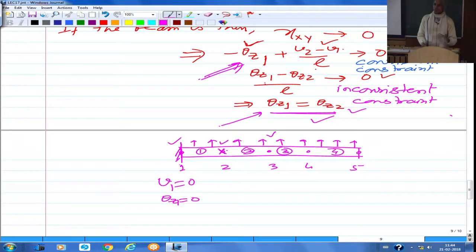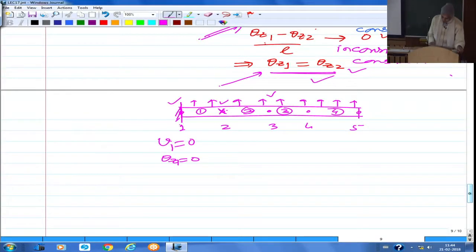So this is the modeling problem when you are using the Timoshenko beam finite element with the kind of interpolation we discussed for solving thin beam problems. Similarly, you can try to argue out what would happen if you have a simply supported beam or a clamped beam, a thin beam, and you are using this Timoshenko beam finite element.